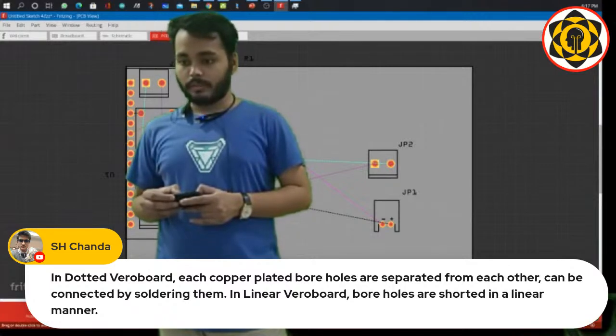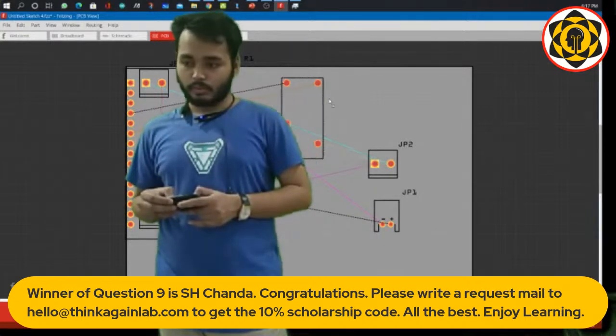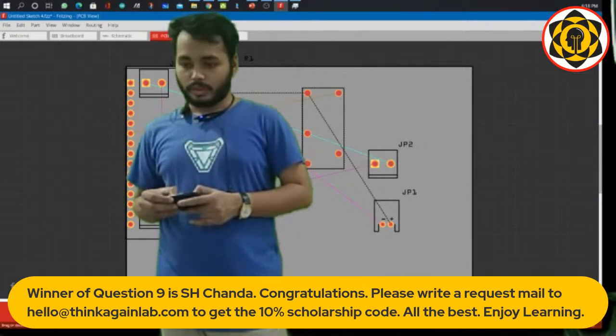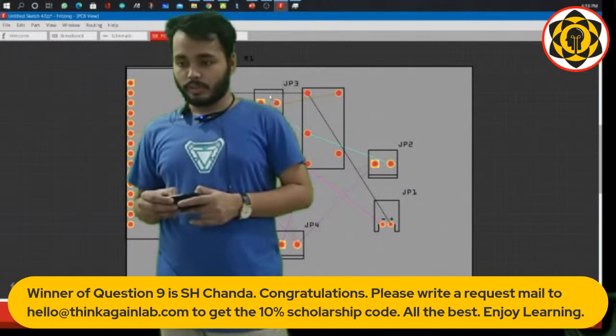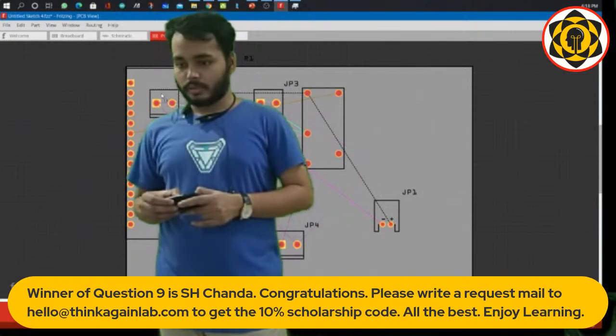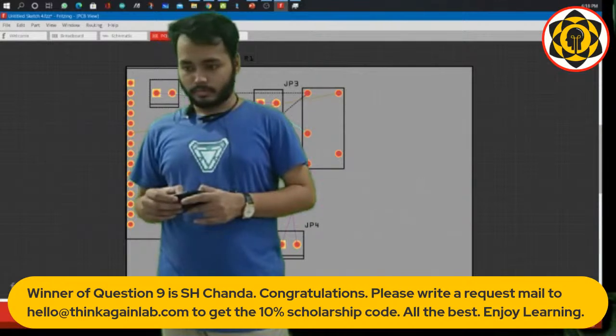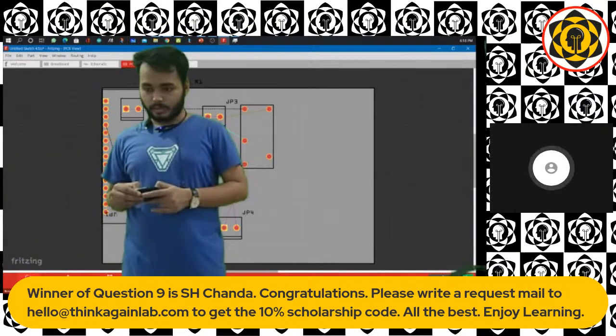Okay, so delete the wire. And no, that will not work. You know why? Because this relay is high voltage stuff on the low voltage side. So yeah, JP3 and JP4 same story as well. These things cannot go over the microcontroller. So what we have to make is like a shield with an extension. Rotate it. Simplify the wiring.